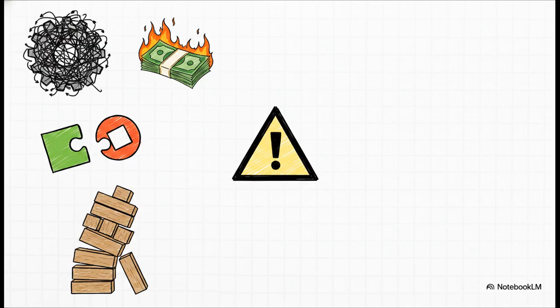Then there's completely mixing up material condition modifiers. Remember, maximum material condition, MMC, is typically for clearance fits. Least material condition, LMC, is often to protect minimum wall thickness. If you swap those around, you're asking for functional failures. Finally, ignoring downstream tolerance stack-ups or forgetting to update the GD&T when you tweak your CAD model, those are surefire ways to get a whole batch of rejected parts.